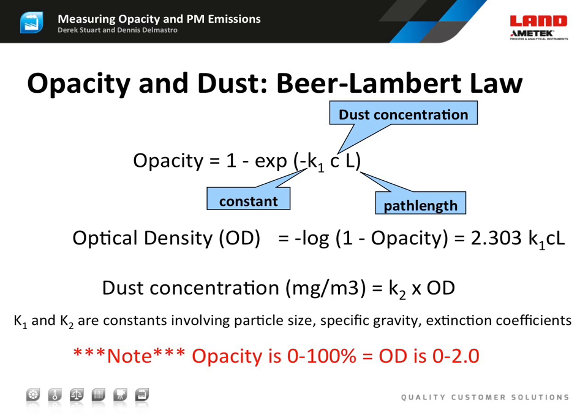As air pollution control equipment, such as baghouses and electrostatic precipitators, improved in their particulate removal efficiencies, the levels of opacity begin to drop towards the 10% opacity levels. At these levels, the particulate concentration of dust in the flue gas are low enough where opacity readings are more difficult but not impossible. Therefore, opacity monitors can actually be used to measure particulate concentrations. However, there is an absolute lower level.